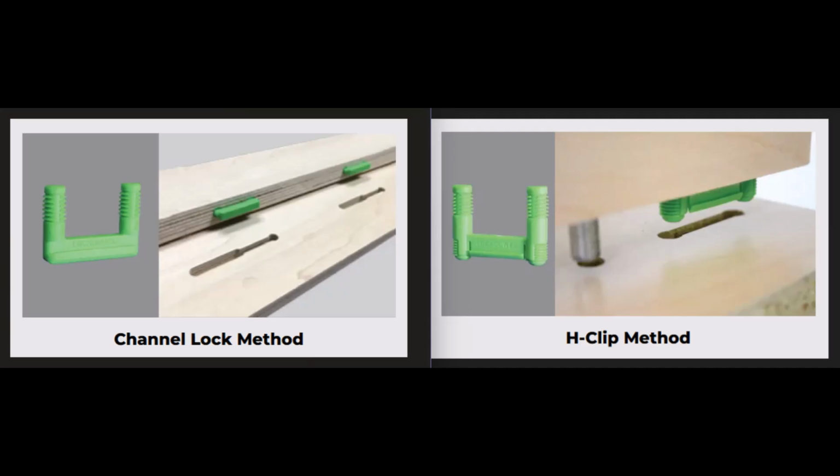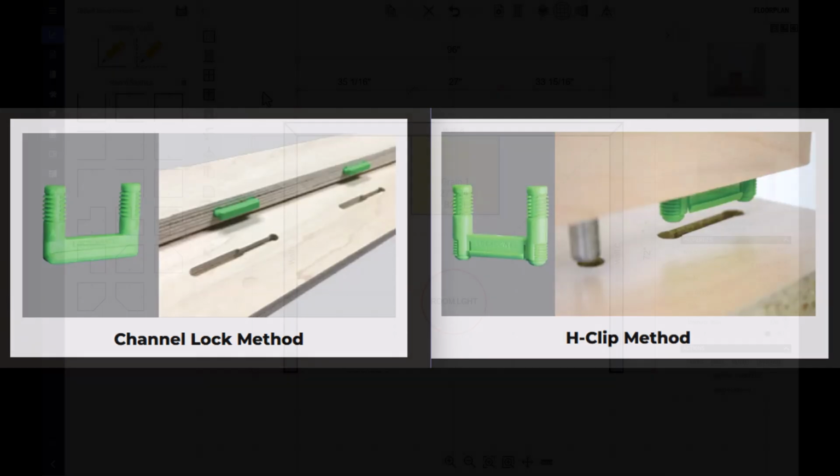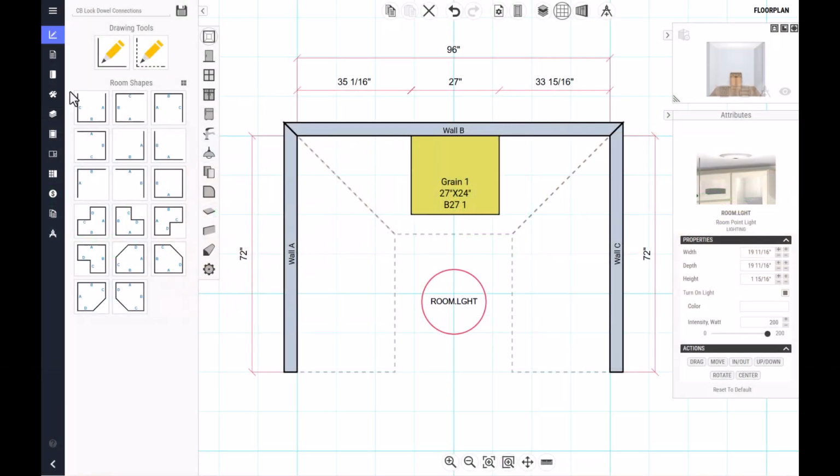The lock dowel pinholes and any enabled spring pin holes also include edge boring operations. Since most standard CNC routers cannot perform edge boring, those holes may require a separate machine or a separate machining process. Let's see how this works.